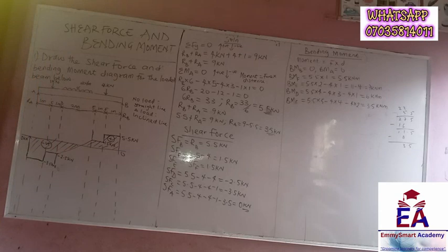So now let's draw the bending moment diagram. So I believe this is clear. Remember, we had to draw a straight line here. Then we had an inclined line, basically because of this distributed load here. That gave us this inclined line here.